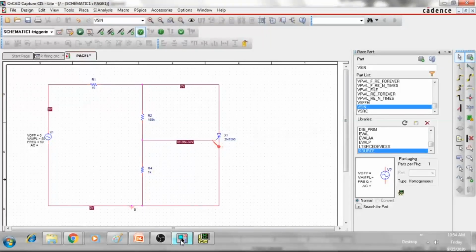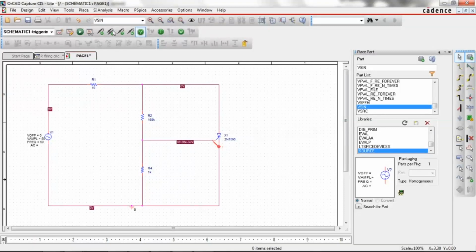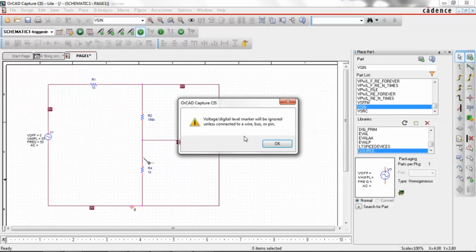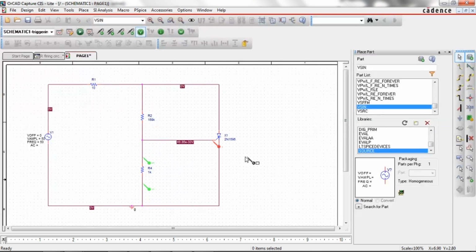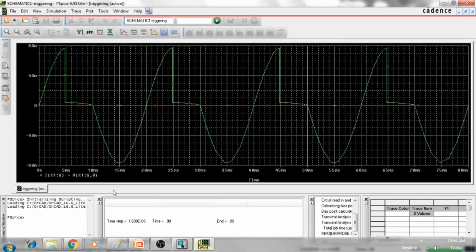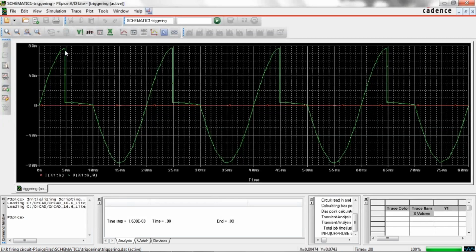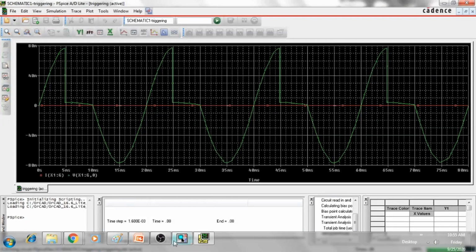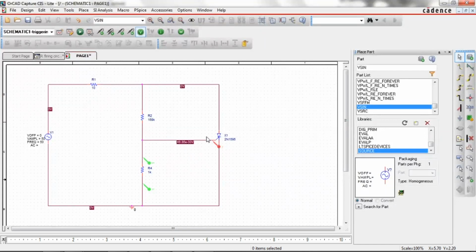Now remember, the voltage generated here, see here, if you go to this, see exactly at 5 milliamps, whatever voltage is generated across that resistance has reached its peak, which is near 0.75 volts, 0.75 volts. Once 0.75 volts is reached across that resistance connected across the gate, that is enough to turn on the SCR. Whatever voltage you give between the gate and cathode is enough to turn on the SCR, and it will supply enough current to the gate terminal.